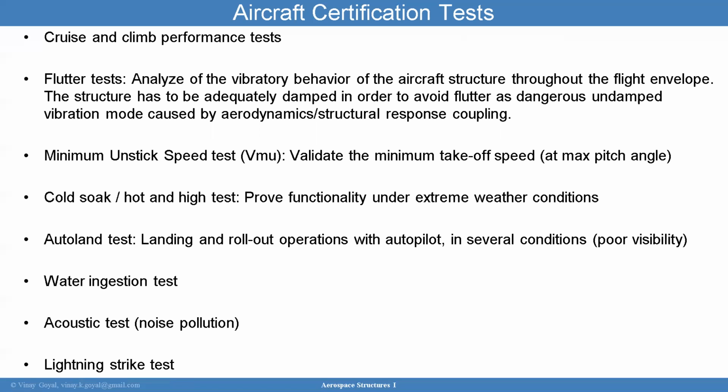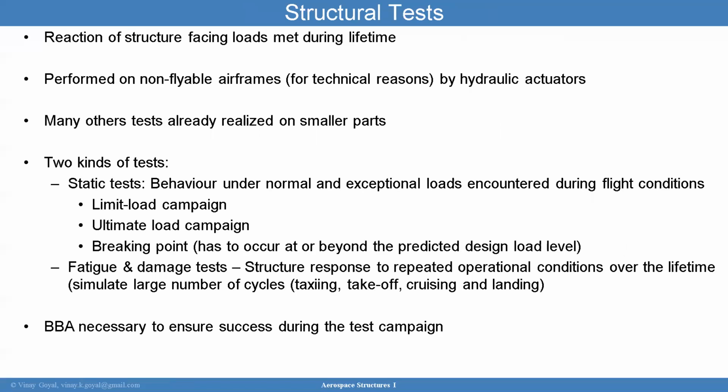and many other tests. There are structural tests in nature, like pulling and pushing a wing, fuselage testing, pressurizing the fuselage, and things like that. Structural tests include the reaction of structures facing loads met during their lifetime. You also want to perform some of these tests on non-flyable airframes by hydraulic actuators. Many other tests are also performed on smaller subcomponent level parts like valves, piping, and things like that.